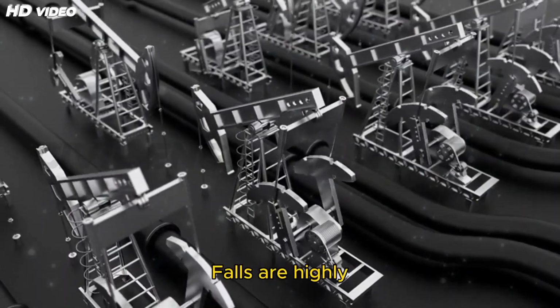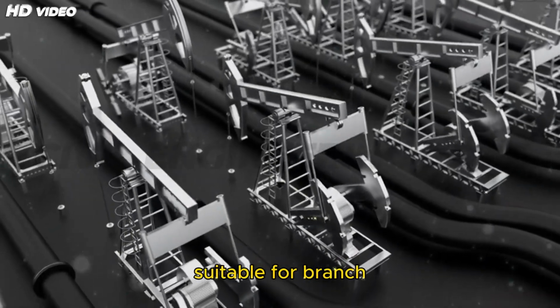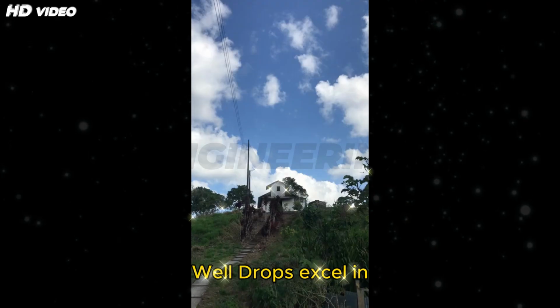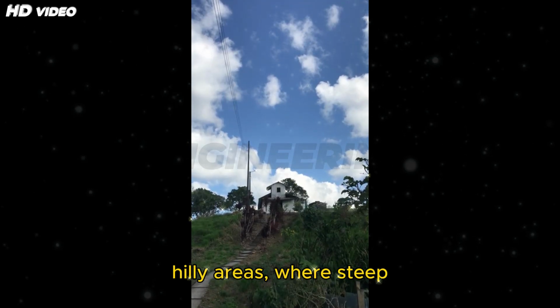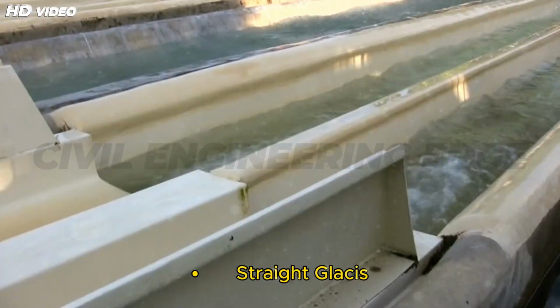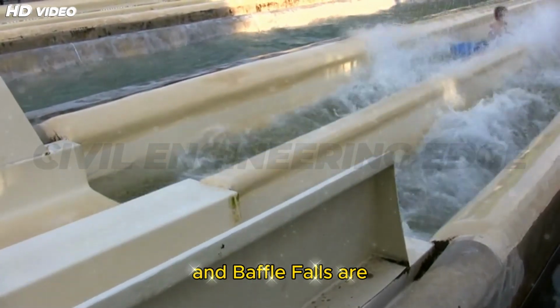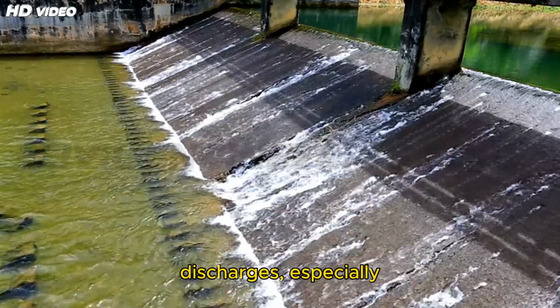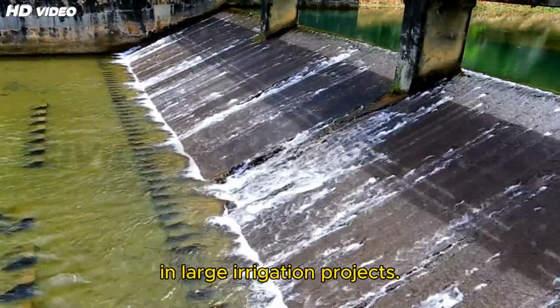Sarda type falls are highly suitable for branch canals, offering modular and scalable designs. Siphon well drops excel in hilly areas, where steep drops and compact structures are needed. Straight glacis and baffle falls are best suited for main canals with high discharges, especially in large irrigation projects.